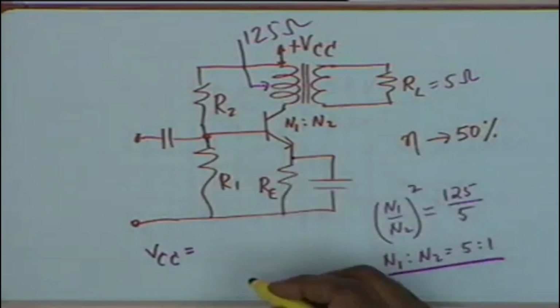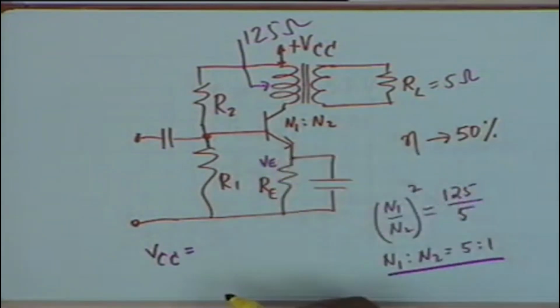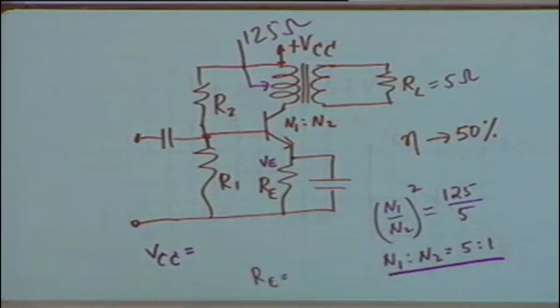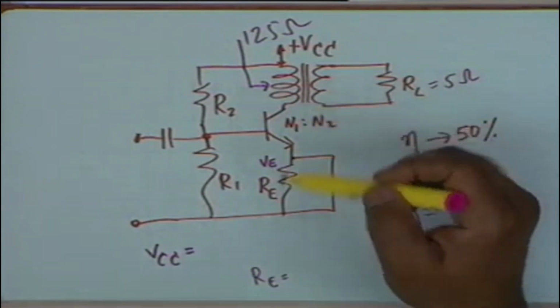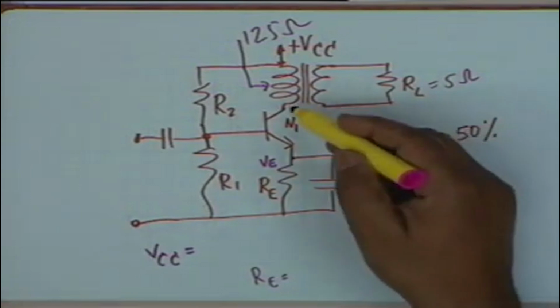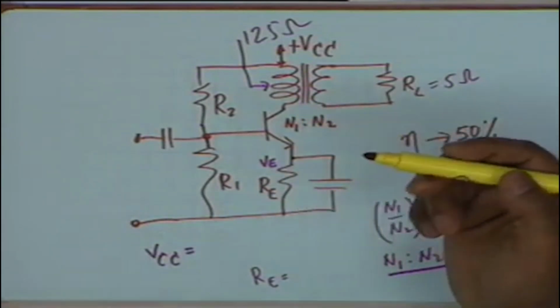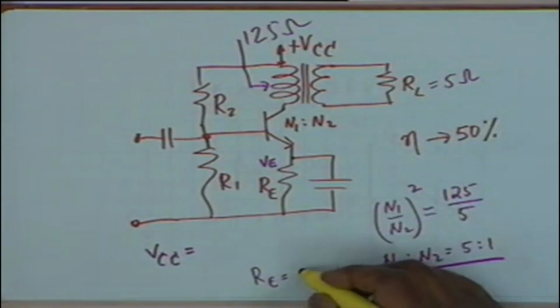If we set VE at 3 volts, then obviously RE needed shall be equal to, the current is 0.2 amperes, 0.2 plus 0.2 divided by beta, but since beta minimum is 30, we can ignore that term, and therefore what shall be RE?